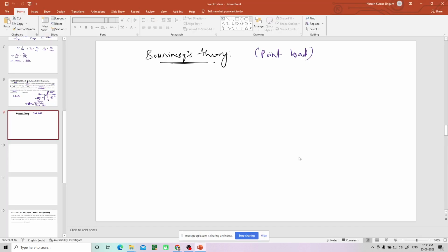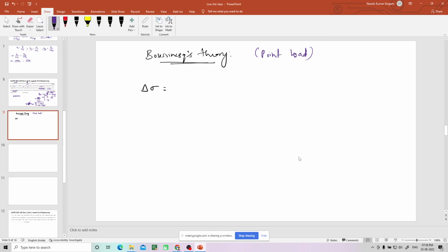Yeah, see, sorry, that is deleted actually. There is some problem with this. I'll check later in the next class. It will not repeat. So I'll just write 3 by 2 pi, 1 by (1 plus (r by z) square) whole power 5 by 2, then into Q by z square.